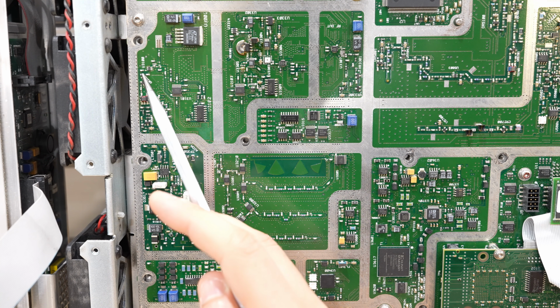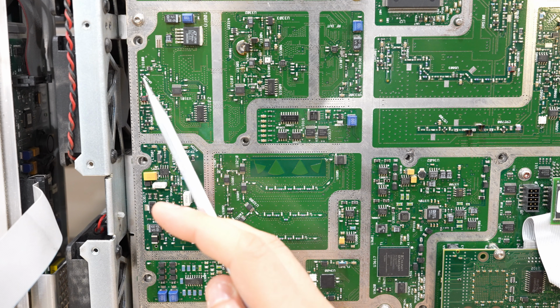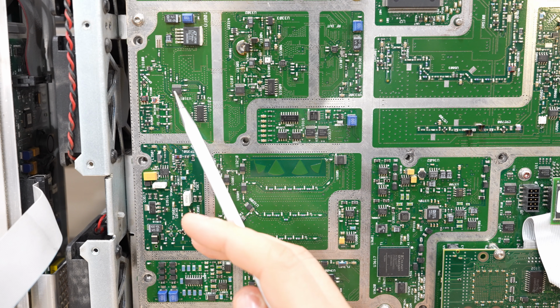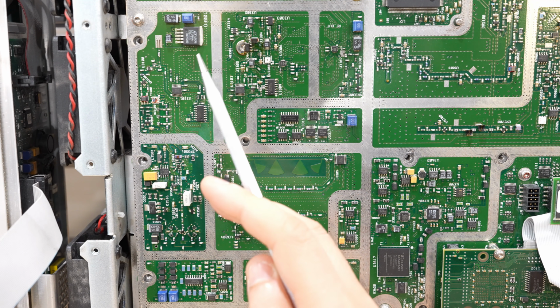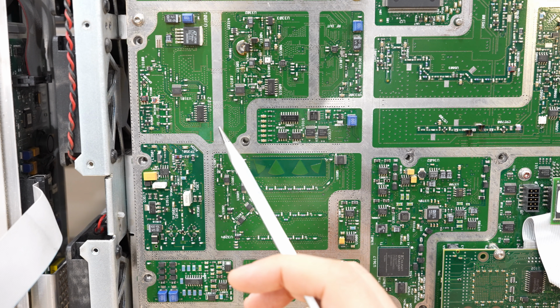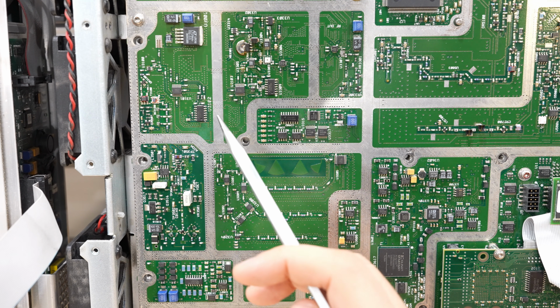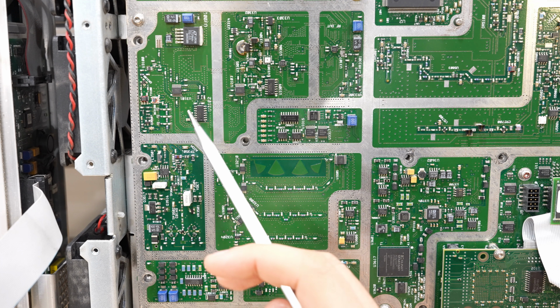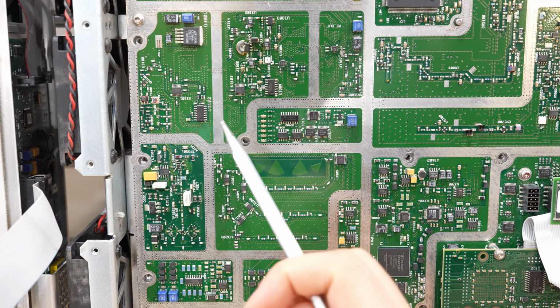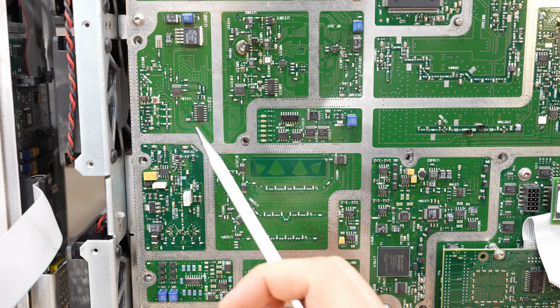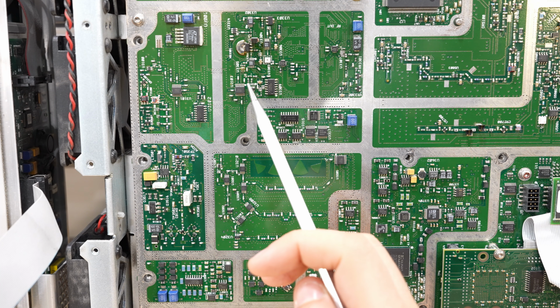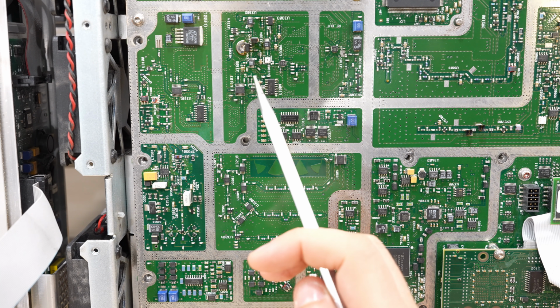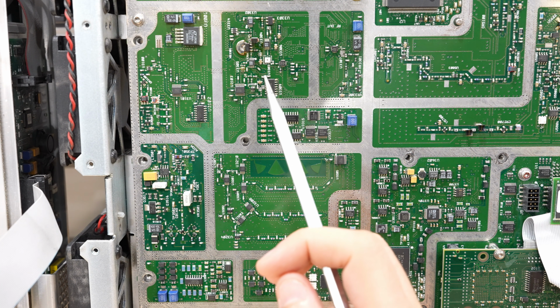So this is pretty tricky because the doubler is in this entire tiny little section. And then it goes over here. This is a switch, and this is a switch, and in between them are multiple bandpass filters, which we saw in the block diagram. They're all buried inside. This chip controls this guy, this chip controls this guy, 2 bits to control them, and then that entire section makes up that doubler and filter. And then over here, they do something interesting. They split it off just using a resistive splitter. We saw that in the block diagram as well. They just tap it off, basically.